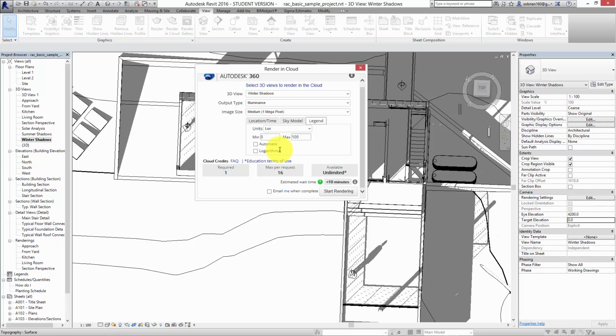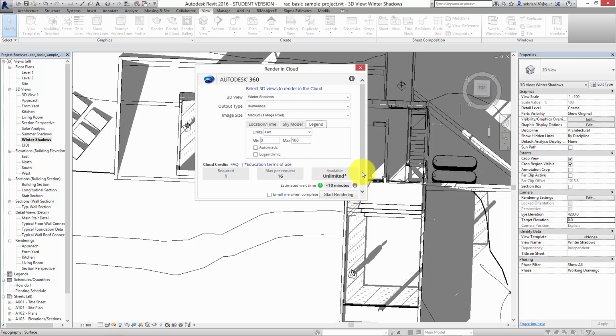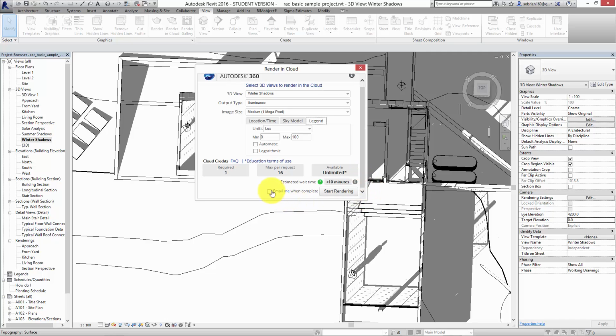So we make one image with a certain construction in the walls, certain type of windows, maybe certain type of sun shading. Then we make another option, which is a different type of sun shading, and then you compare the two. And that's the best concept stage design analysis that you can use, because at least then you have a piece of evidence you can go to your client with and say, this is evidence-based design. We've made these decisions based on this analysis by this program, which is registered and has been analyzed to show that it is actually very, very close to reality. And once you do that, let's just leave it at that.